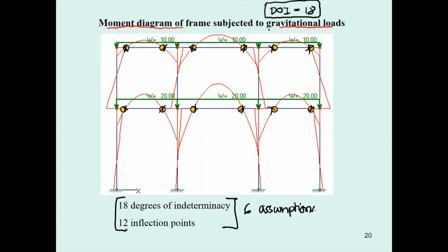And since the frame is subjected to only the vertical load, let's say this is vertical load, the summation of the force in the x direction can be approximated to be 0. So by using the summation of force in x equal to 0, you get 3 equations, let's see, just for the beam, that is 4, 5, and 6.